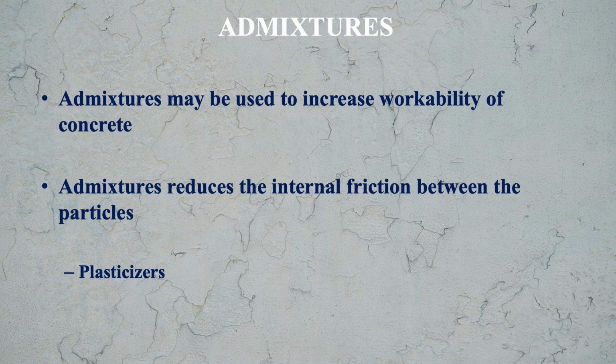These are some compounds which give the lubrication effect, and due to this lubrication effect, the internal friction between the particles is reduced, and because of that workability increases. And various admixtures like plasticizers, superplasticizers, air entraining agents can be used for increasing the workability. And about these admixtures we will learn in another module in detail.